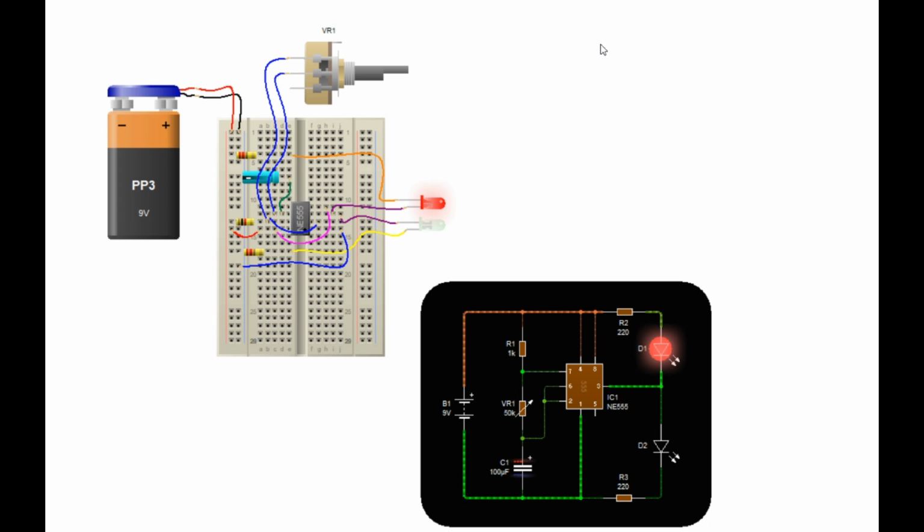Trigger reached. When the voltage across C1 drops to 1/3 of the supply voltage, the trigger comparator inside the 555 timer triggers, causing the output to go high again. 6. Cycle repeats. The charging and discharging cycles repeat indefinitely, generating a continuous square wave at the output.